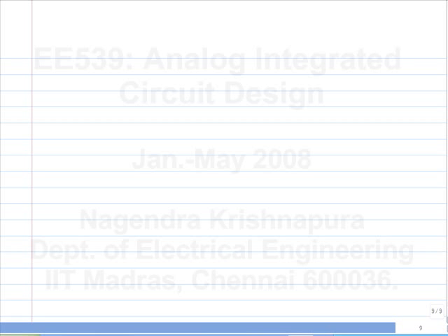Okay, and you multiply the spectral density of individual resistor with the magnitude squared of the particular transfer function, and add all of them up.